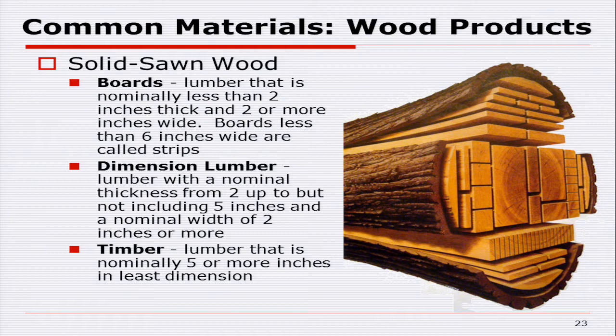If you go and ask for a 2x4 and you measure it, its size is going to be very close to 1.5 inches by 3.5. That's what we call an S4S 2x4, and don't worry about the S4S. It stands for surfaced on 4 sides. Although it is actually less than 2 inches, nominally it is supposedly 2 inches, so it falls under the category of dimension lumber.